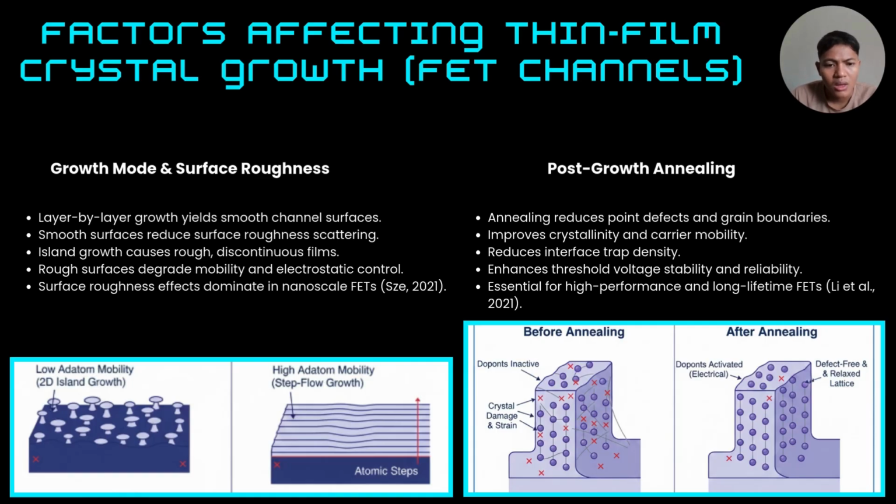And post-growth annealing reduces point defects and grain boundaries, improves crystallinity and carrier mobility, reduces interface trap density, and enhances threshold voltage stability and reliability, essential for high-performance and long-lifetime FETs.